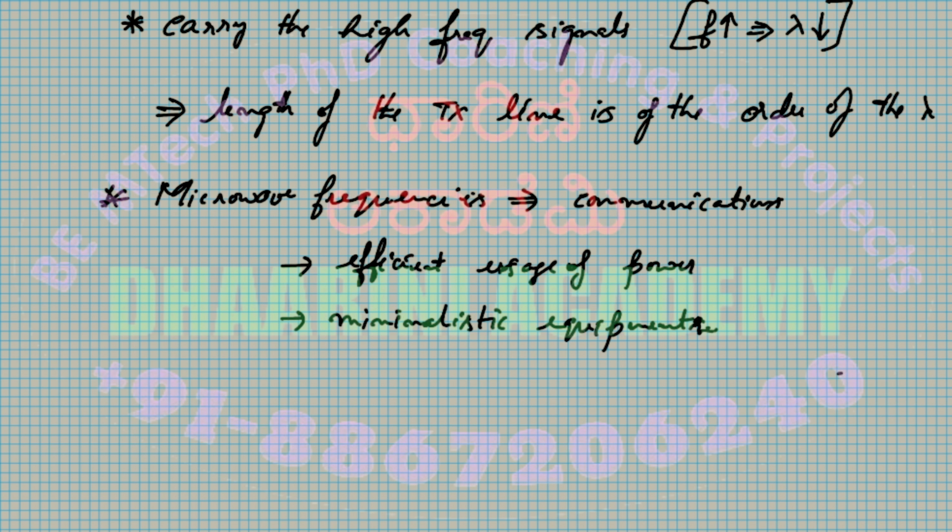Between them, to connect, we cannot use a simple line. A simple wire cannot be used because it's not going to match. We have many conditions like input impedance, output impedance, etc. That will not match, and it will lose the power which is given as input. So the final connection just before the antenna should be very perfect, to carry the signal without any losses. For that reason, we are looking at that.